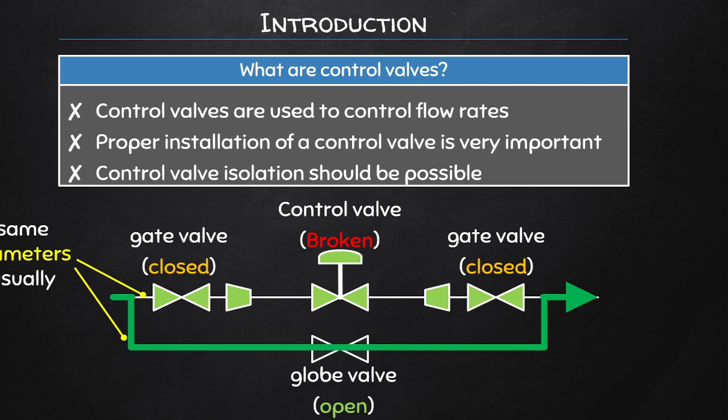When the control valve is in use, it is also very important not to allow the gate valves to be left in any other position other than being fully open. If this is not the case, then the edge of the gate that blocks the flow can be eroded away over time. So it's like holding your hand slightly into a stream of flowing water. Eventually your skin will start to get soft. The skin can then, if the flow is hard enough, tear away. So it's kind of the same thing.